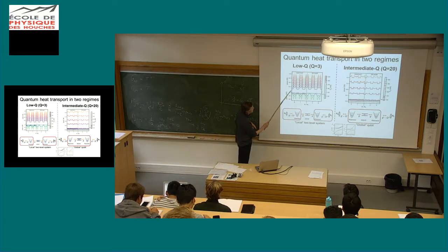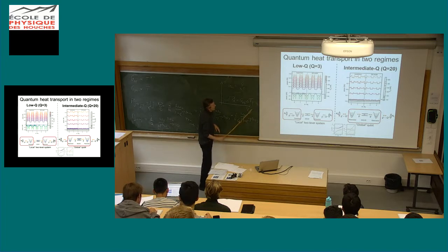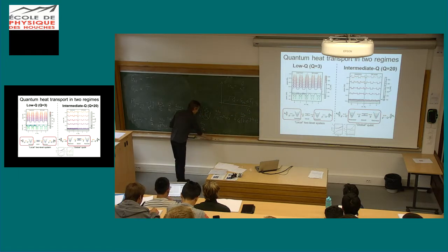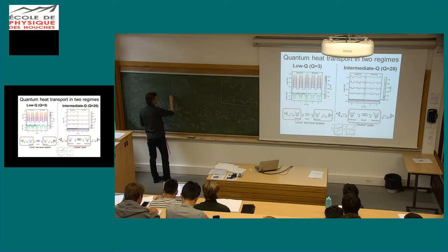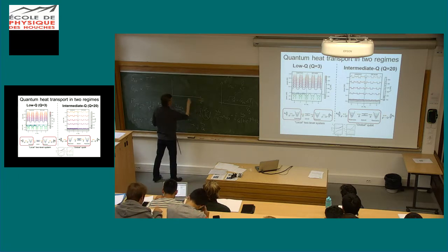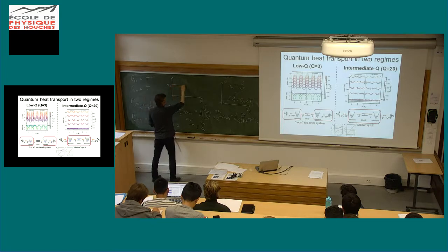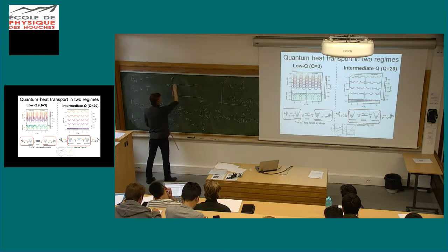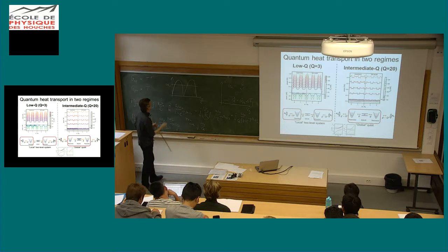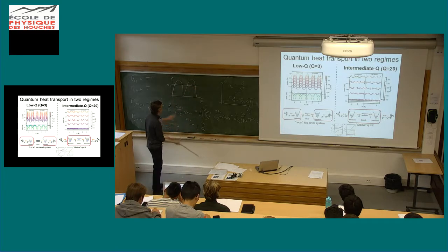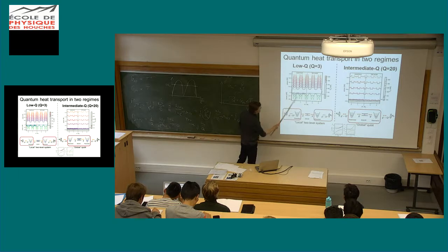And we can see that at different temperature biases, there is a modulation of this power with magnetic flux, and it really corresponds to what we would expect from this simple model with the Lorentzian filtering. So in fact, as a function of magnetic flux, we have the energy. The frequency of the LC oscillators is fixed, and then we have the energy of the qubit, which, due to this flux dependence of the SQUID, is crossing the resonance of the LC oscillator twice in each period, and that's why we see 2 peaks in each flux period here.